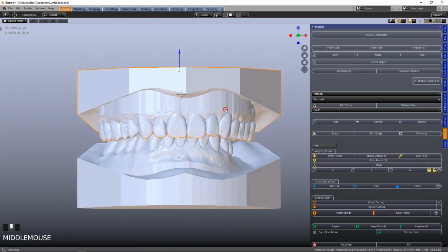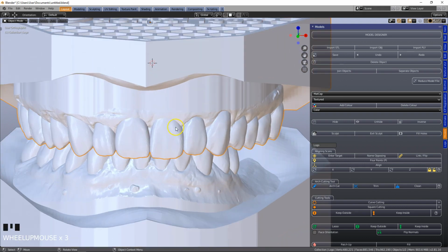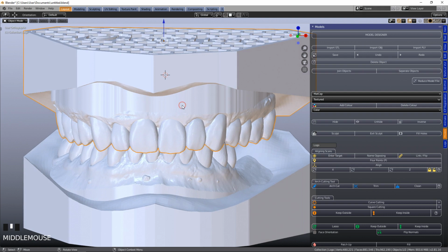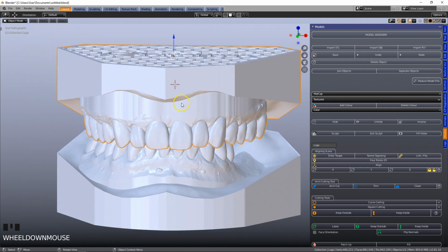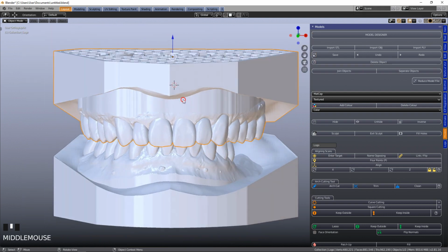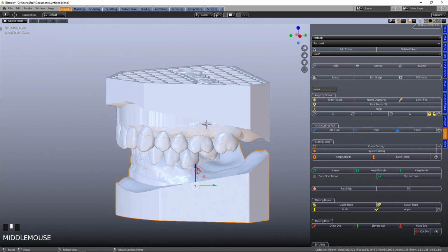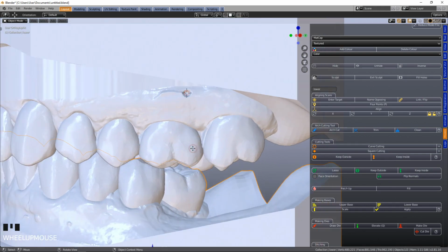If you don't want to do that, you can just select these components, each object that you want to group together, and just file, export STL file. The STL file will join all of these objects up together for printing anyway, so you don't really necessarily have to do this procedure. If you do want to further improve the way the model looks,